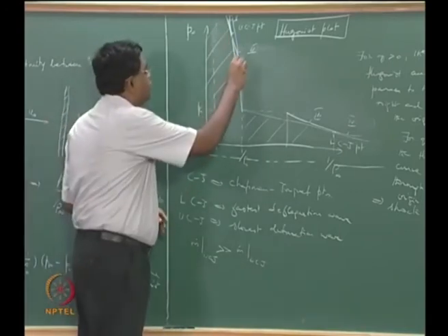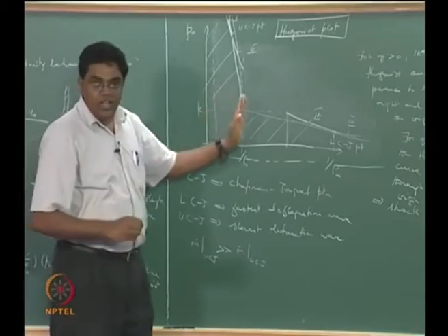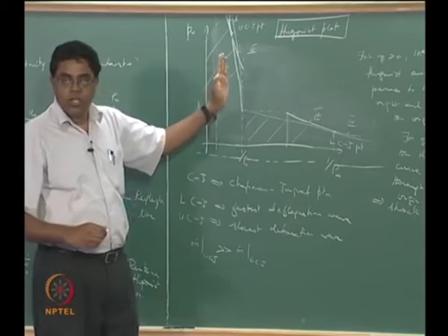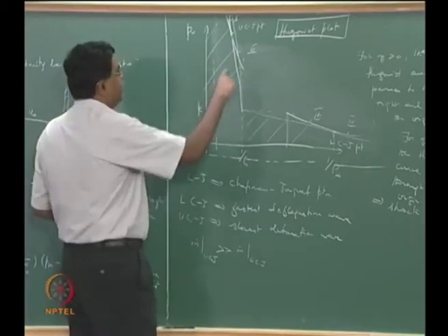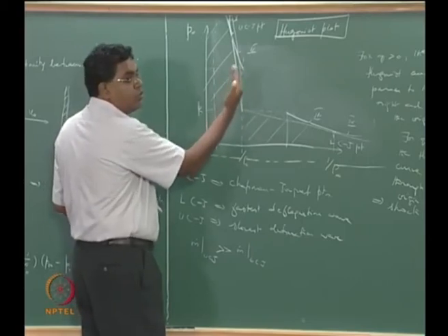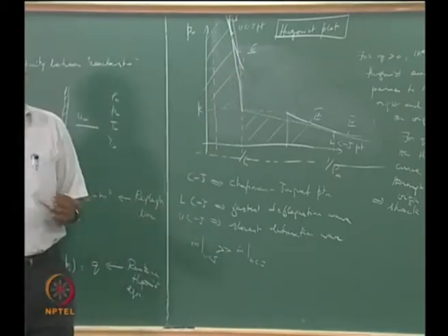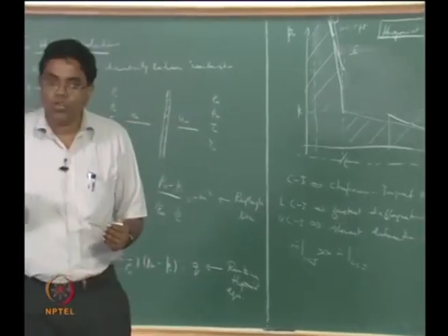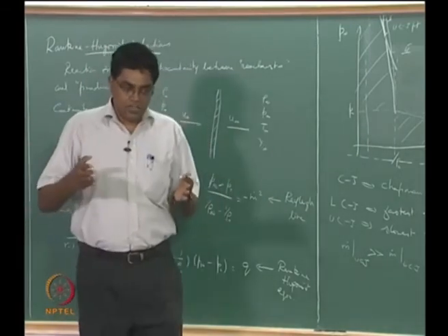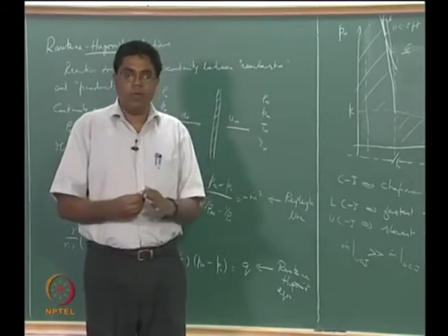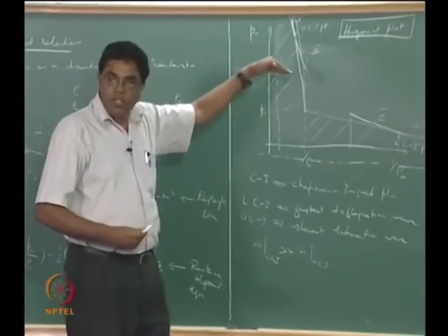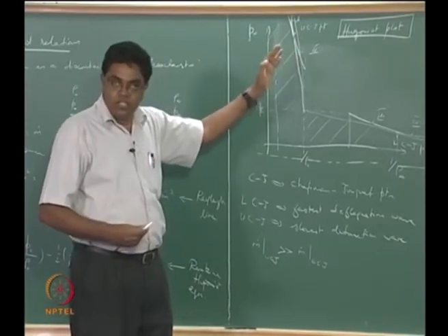If you were to now look at a solution that is here, its Rayleigh line is pretty steep as well, just as steep, so it's pretty fast alright, but it is not leading to a very high pressure, and the departure from the origin is not a lot in the 1 over rho infinity axis. So your 1 over rho infinity is not a lot lower, therefore the rho infinity is not a lot higher, therefore you are having a smaller amount of compression when compared to the strong detonation. So relatively speaking we would like to think of this as a weak detonation.